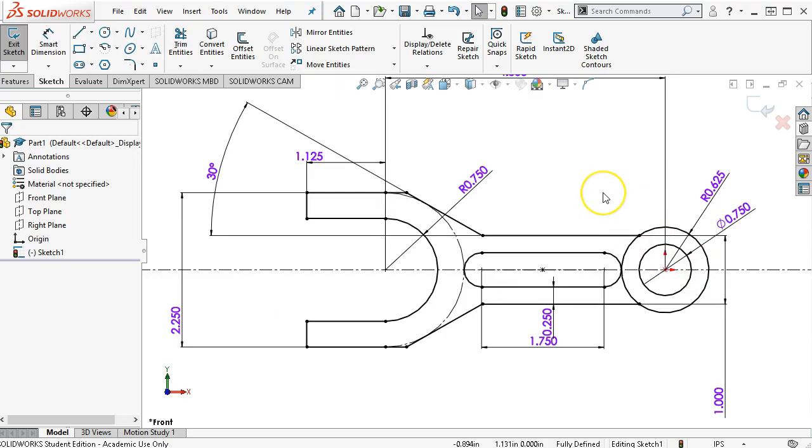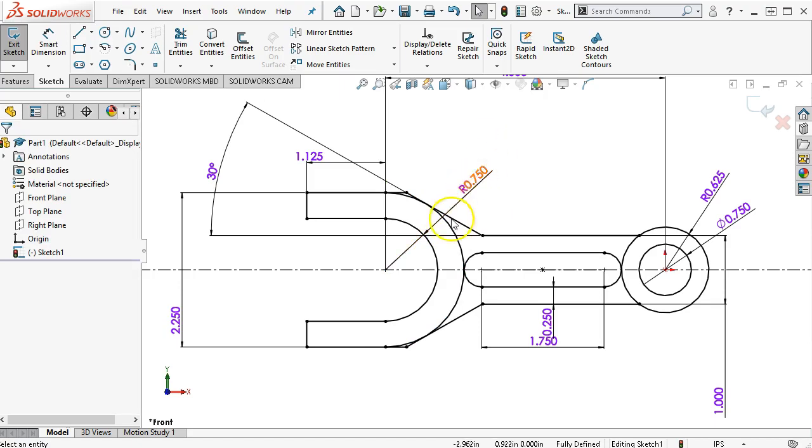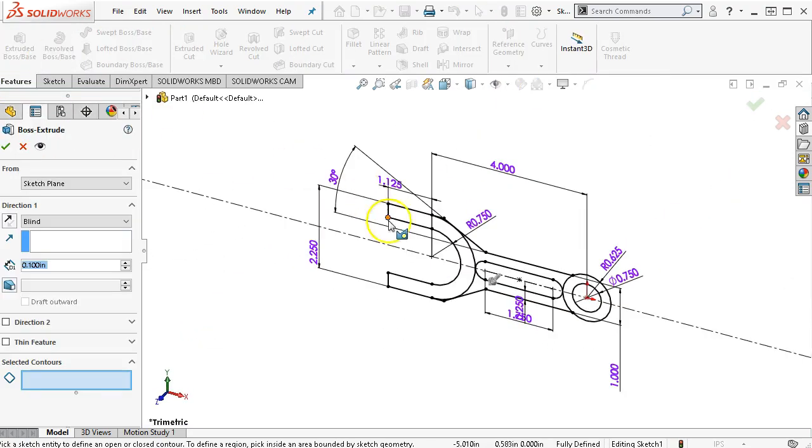All right, I think that gives me the majority of the geometry minus the fillets. If we wanted to, we could convert that back and use it as part of our build and eliminate the fillet there. So let's go ahead and see what we get. I'll leave it with the contours and regions. So blind condition, thickness is 0.5.